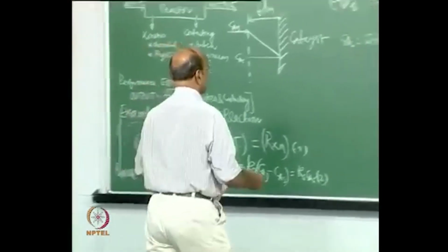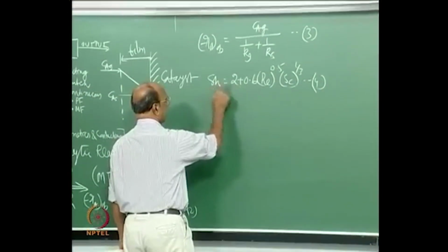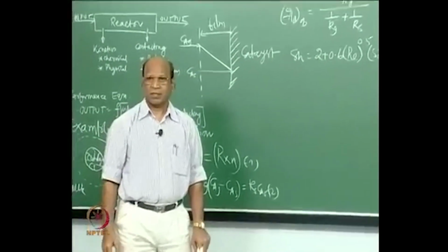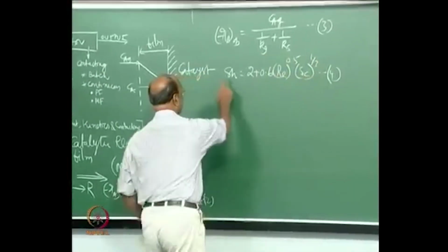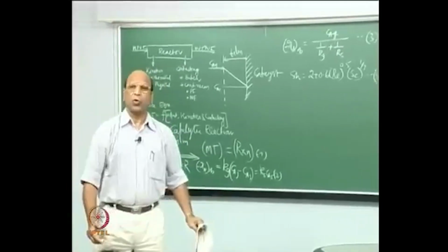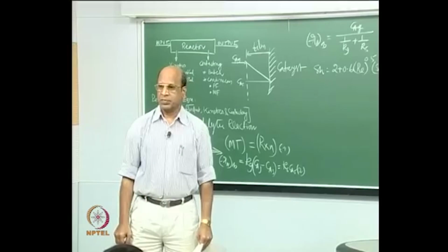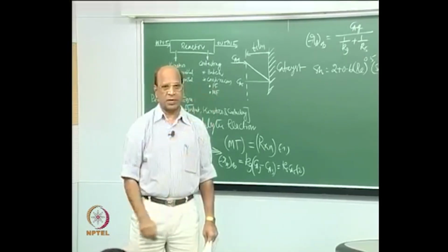So, that means now you can find out how Kg is varying with dP. This term is totally neglected. So, I have here Kg dP by diffusivity, then you will know Kg is inversely proportional to dP, right, because dP will come down here.